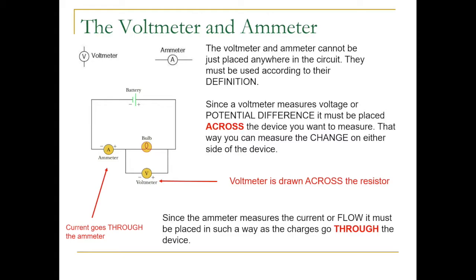At the other end, with a voltmeter, we have it hooked up to a digital device. We don't want any current to travel through the voltmeter. We want all the current to travel through the digital device so that we can measure the voltage associated with that digital device. Because of that, in theory, the ideal voltmeter is considered to have an infinite amount of resistance.